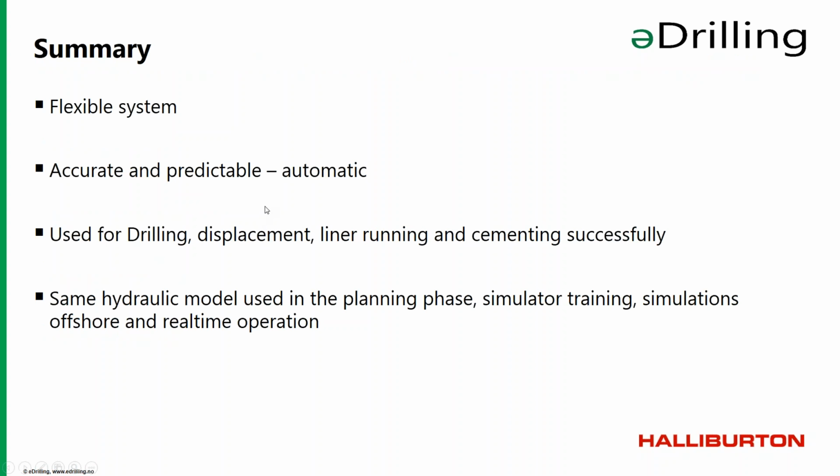So we've gone a little bit through the MPD system, that it's flexible. You can increase or decrease the bottom hole pressure as needed, depending on if you get an influx or loss. You don't need to, as in a conventional system, weigh up or weigh down. You can use it to take a dynamic FIT. You can use it to take a dynamic drawdown test.